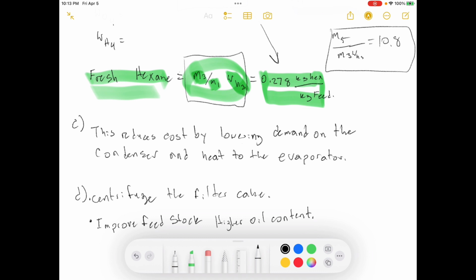Okay. How might the inclusion of this unit lead to a reduction in the operating cost of the process? Okay, so how does this lower your costs by adding a heat exchanger? Well, it doesn't at first, right? Because you're paying the capital cost of a heat exchanger. So you would need to make sure that the amount of money you're saving by getting the heat exchanger eventually pays for the heat exchanger and then ends up saving you money, right? Okay, but that being said, if you assume those things are true, how would it save you costs?